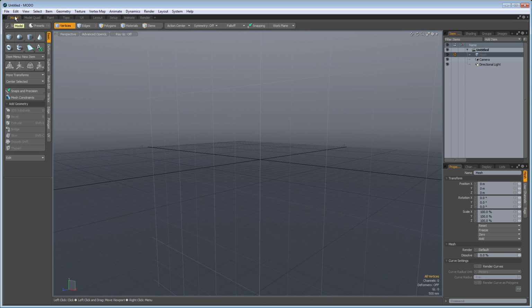Now, no matter if you're in the Model tab or the Model Quad tab, take a look over here on the left and you'll see some tools for making primitives, some transform tools, and some tab tool sets accessible on this vertical sub-tab menu. And this arrangement is on other toolset tabs as well. On the right, we have a couple of tabbed panels. You'll be using these panels extensively for setting up your scenes, creating materials, setting properties, and other things.